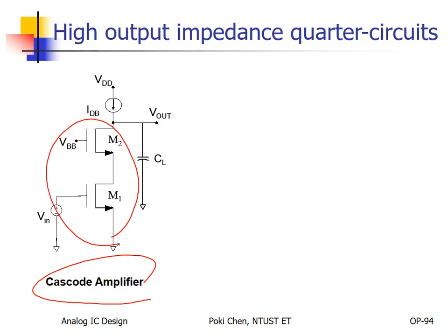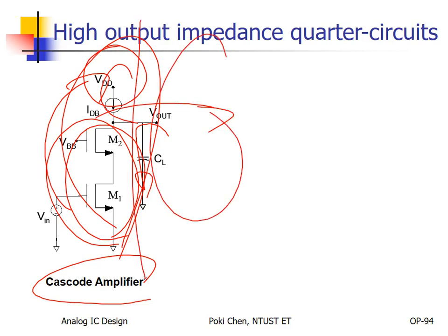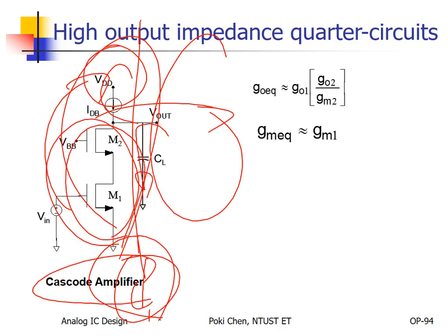In this way, we can enhance the output resistance by almost 2 orders. But this is only the quarter circuit. You need to flip it to become the counterpart circuit. Then you have the left half circuit. Flip to the right to get the other half circuit, and apply your bias current, usually in the middle of the symmetry. That's it.